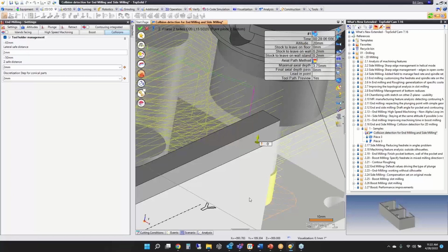The spun profile should be as simplified as possible, because if you have a really complex profile for your tool definition, it's going to add to the calculation time. So just keep that in mind.